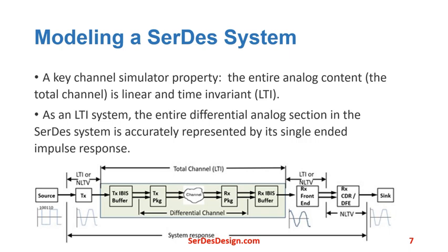Modeling a SerDes system. A key channel simulator property to keep in mind is that it considers that the entire analog content, the green area in this figure, the total channel between the transmit AMI portion and the receive AMI portion, is linear and time invariant. As an LTI system, the entire differential analog section in the SerDes system is accurately represented by its single-headed impulse response. This key concept enables the channel simulator to achieve its fast simulation speeds.